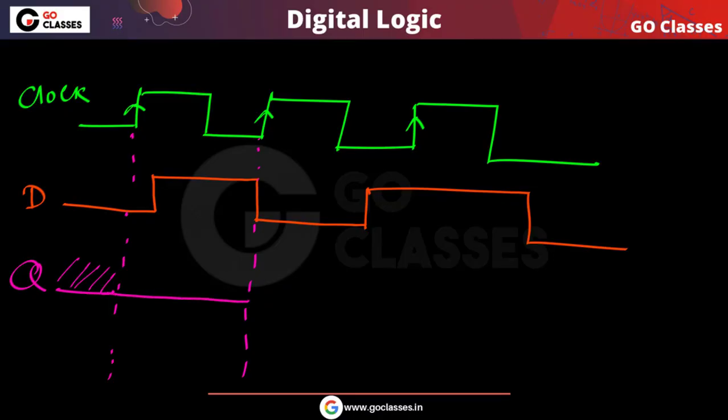Now you can notice there is a problem here. Here there was no problem, because during this rising edge we already know that the value of D was already 0. But during this rising edge there is a problem. What is the problem? When the clock is going from 0 to 1, during this positive edge, you can notice the D value is going from 1 to 0.